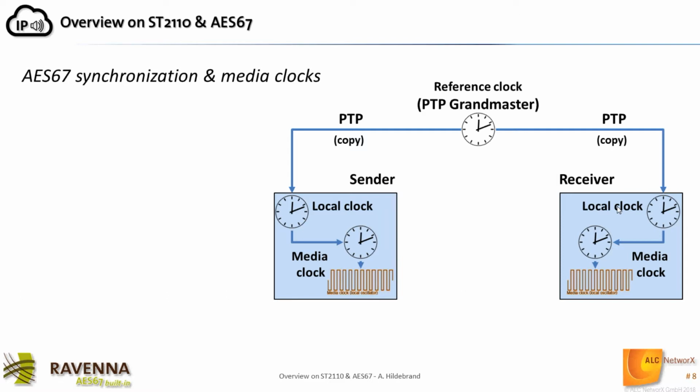And it's not just the frequency, it's also the phase, which is an absolute synchronization to each other. Now, once I have a media clock, let's say a 48 kilohertz media clock for an audio device, of course, I want to generate a stream and send it over to a particular sender. So I generate my stream data, and the way it works is the transport is established with the RTP protocol. The RTP has its own RTP clock or stream clock.